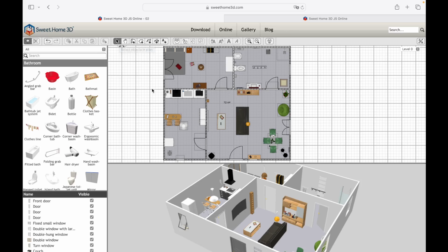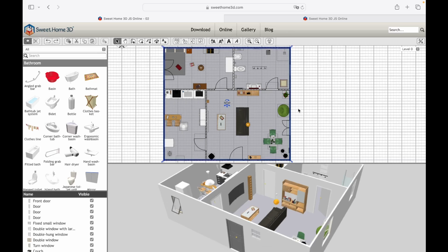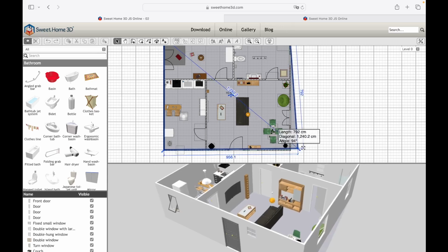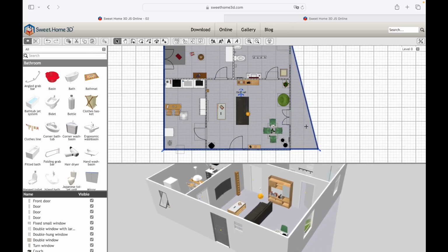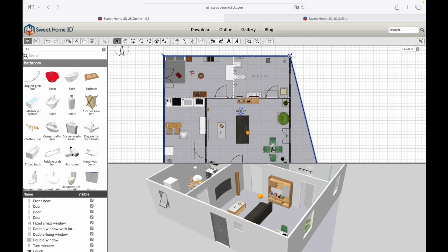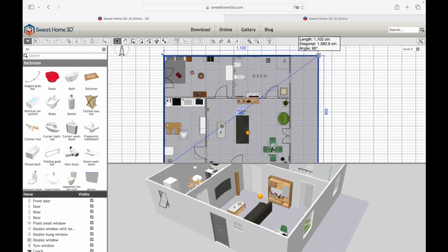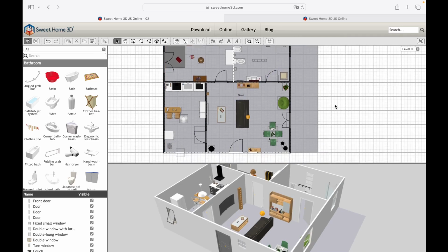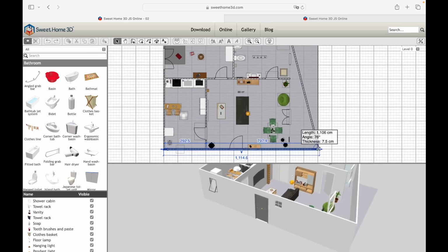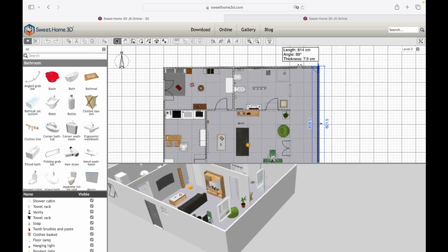First, we click on the surface, then we click and drag a vertex until we reach a distance of 11 meters, and repeat with the other corner to establish the new area. Once this step has been completed, we rearrange the walls of the house in relation to the surface. We click on the neighboring walls of the house and match the corners of the walls with those of the surface.